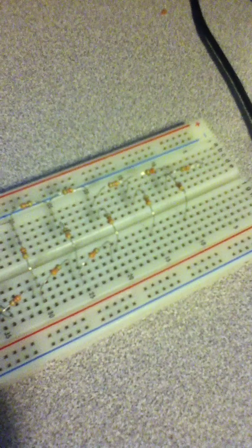It uses pulse width modulation, high speed, to do sort of a ghetto digital to analog conversion, because I don't own a digital to analog converter. I made a bad resistor ladder one here and it sort of worked, but it's only one channel. It has stereo here with 2 PWM channels. The limits on the module file are basically only about 20 kilobytes, because it has to be stored in the flash memory of the AVR on the board there.